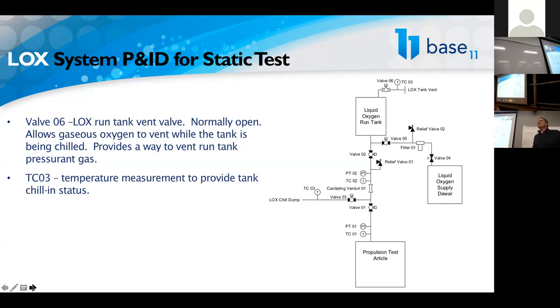The question is, what do we do with the LOX that comes out of the tank while it's overflowing? And we evolved at that. If you look at videos from large test stands, they just dump that LOX into the flame bucket. They just let it overflow and stream into the flame bucket where there's probably water and certainly a lot of concrete, and that boils it off. We don't have that here at Zucrow at Purdue.